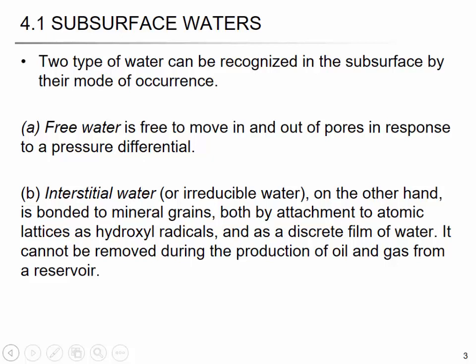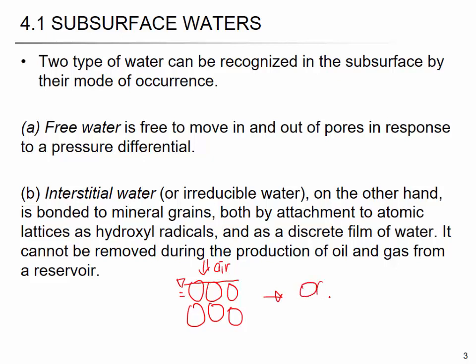For example, imagine that you have a soil full of water, and you blow it with air, then you have some water remaining at the meniscus, right? So there will be a limitation in removing the water by flowing the air, right? And that's called the residual water saturation.